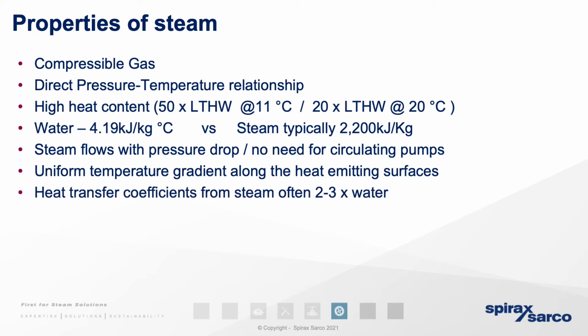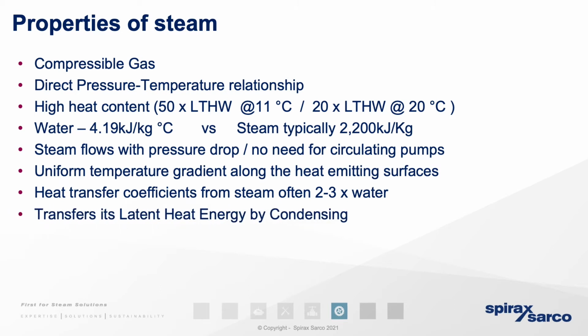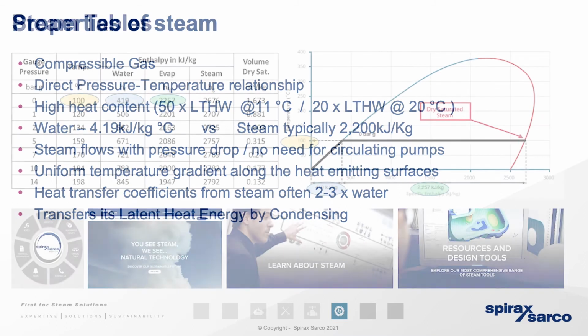Steam also has a very high heat transfer coefficient. In other words, the rate at which it transfers that heat energy is very fast compared to a liquid system, as much as 2 to 3 times as fast, in fact. And we also know that steam transfers that heat energy through the latent heat energy that it gives up at the process. It does that through the process of condensation at a constant temperature.